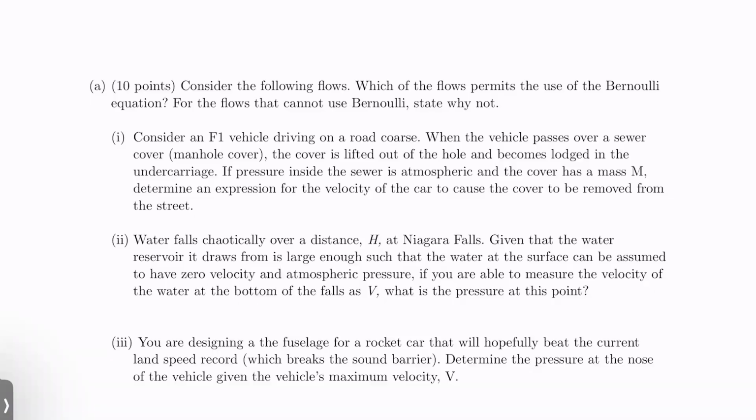If you remember when we talked about the Bernoulli equation, the assumptions we made to come to that equation were: we had to have a steady flow, it had to be an incompressible flow, and we had to be able to follow a streamline, meaning it has to be laminar, essentially. Those are the big 3. Okay, so let's consider our options.